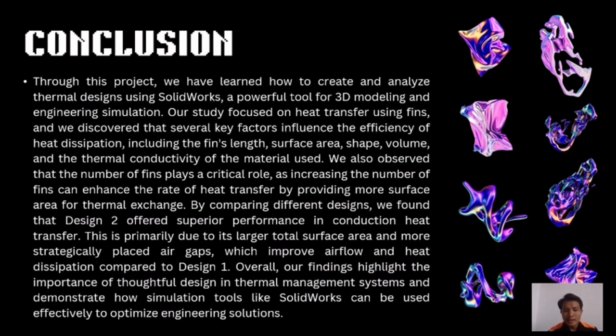Throughout this project, we have learned how to create and analyze thermal design using SolidWorks, a powerful tool for 3D modeling and engineering simulation. Our study focused on heat transfer using fins, and we discovered that several key factors influence the efficiency of heat dissipation, including the fin's length, surface area, shape, volume, and the thermal conductivity of the material used. We also observed that the number of fins plays a critical role, as increasing the number of fins can enhance the rate of heat transfer by providing more surface area for thermal exchange.